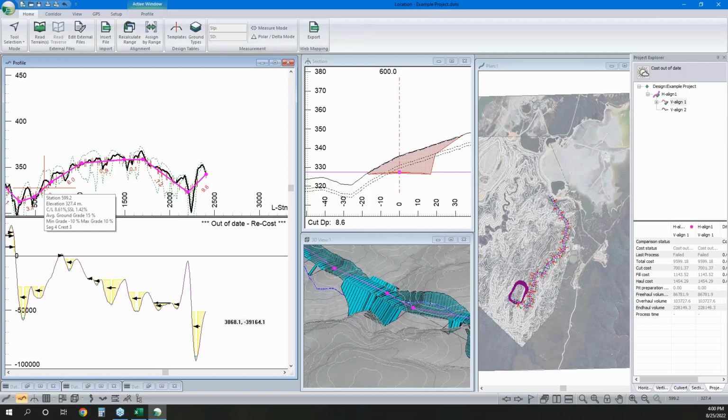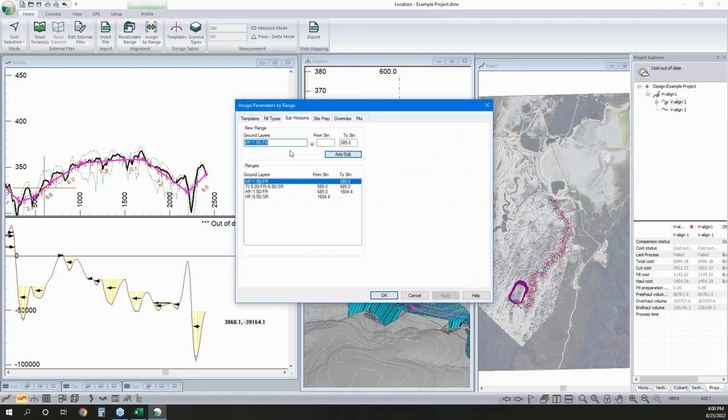So our road is basically 30 centimeters too high. So being 30 centimeters too high, we're cutting less material just because it's not being tracked as subgrade cut, but we have to account for that material that was no longer there now too. So that's where that balance gets out of whack.